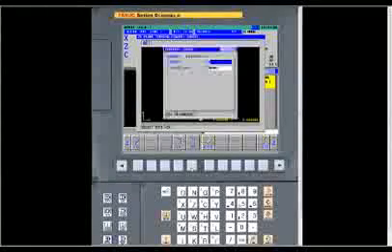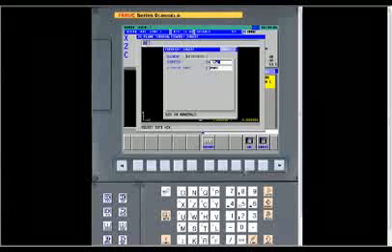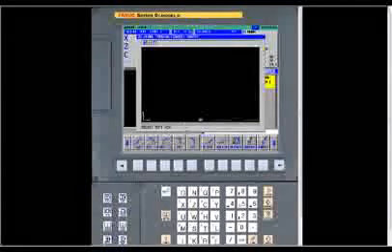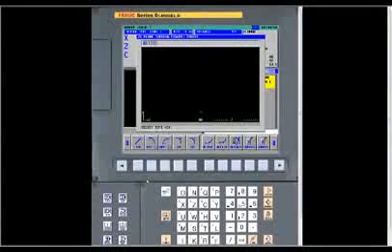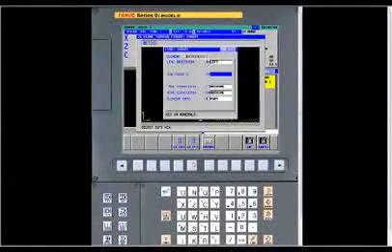But we do want to put a corner chamfer because we're going to chase threads on this side. So we'll put 0.125, an 1/8 inch wide chamfer. It'll be 45 degrees. Again, it didn't draw it yet because it doesn't know which direction to go yet. So we say line to the left, and we'll say minus 1.575.